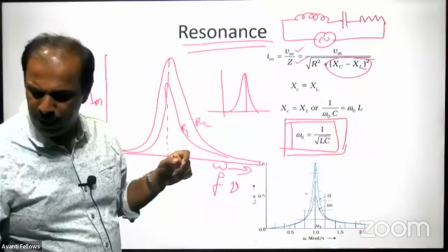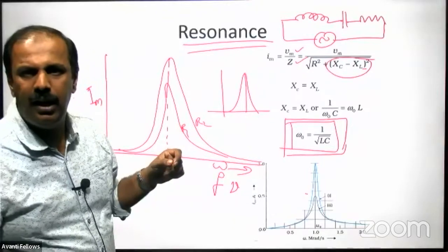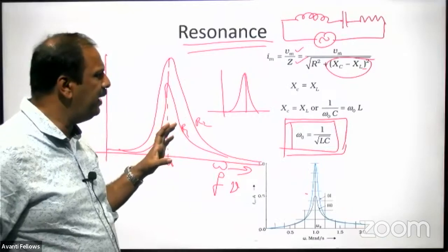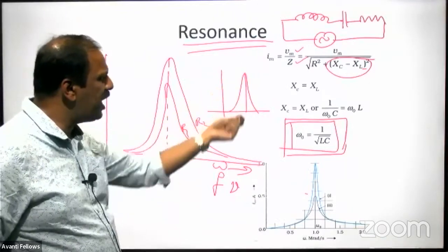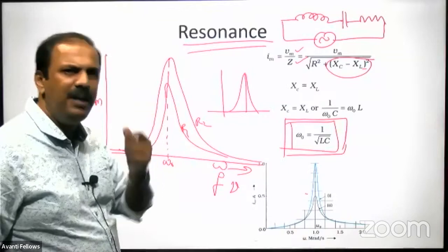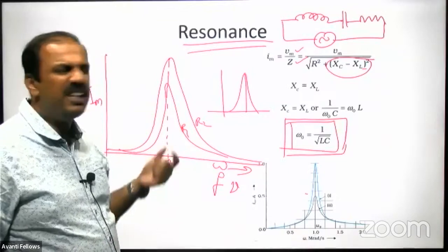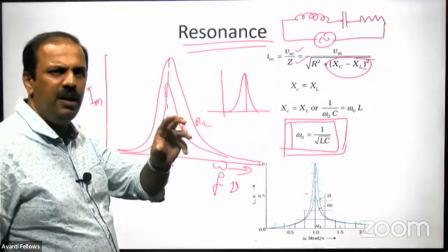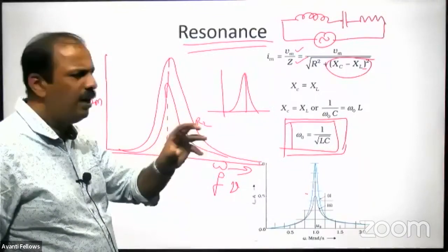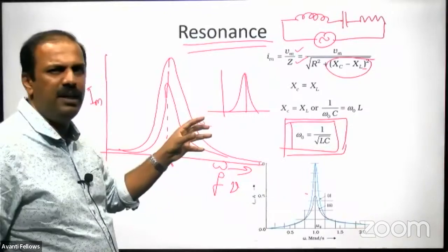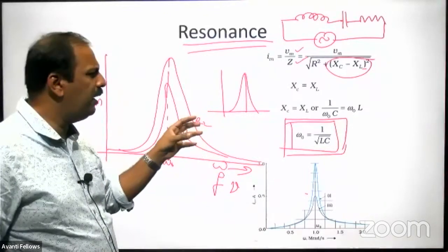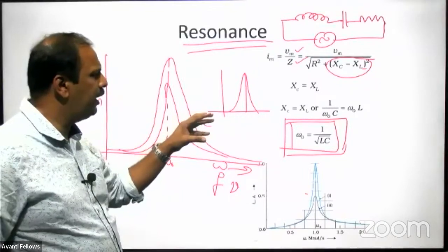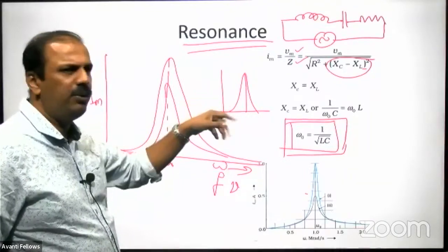When you are tuning, you are physically changing the value of capacitance in such a way that we select a particular sharp value, so that only that channel will be selected. When you change the capacitance, you have something to rotate there. When you change that, you are changing the channel, so you get a different value of capacitance. According to that, you can tune.